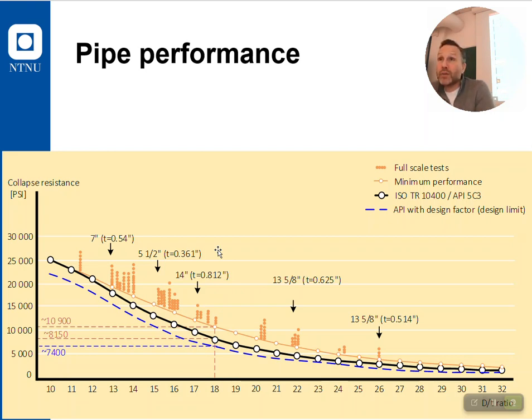permanent deformation, right? Yep. And now we say that, just as an exercise, because this is collapse, and these pipes are not having a pure yield. They also have this geometrical part, right? But if you think about this picture as a purely loads to yield question, this is the point where you start to yield, right?